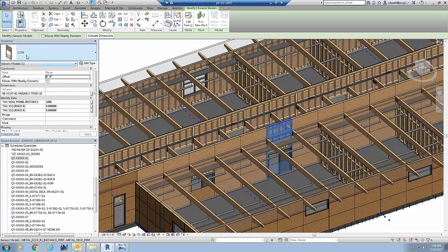So this .99 ultimately has a parameter that's embedded in it that says what SKU it was placed for. And so then I know the SKU's rough opening, and I can create a panel based off of that, right? We've created placeholders just so we can offer more types, because we don't know what people are going to want to use. In certain districts, we do mostly schools under these configurations right now. So certain schools might have a certain opening that they have to use. And for the custom SKUs that we'll be adding, you just type in the size, and in theory, the panel would parametrically adjust to that rough opening.